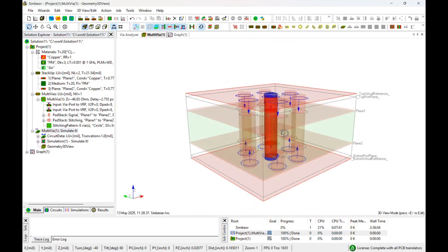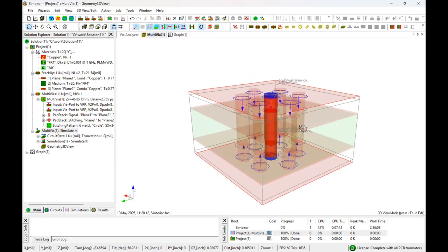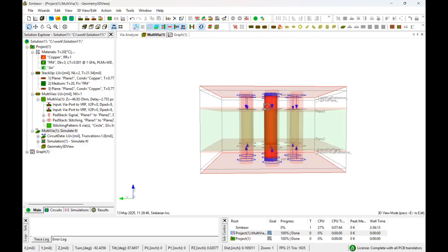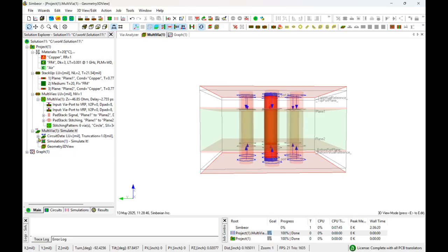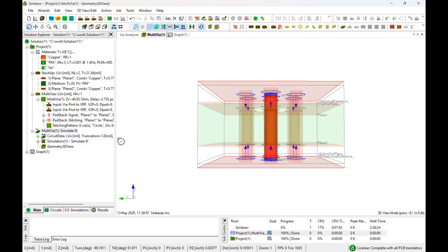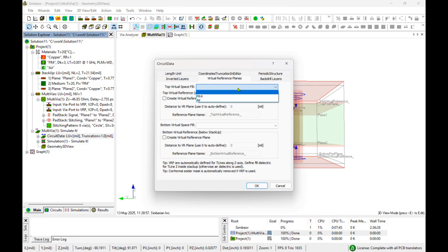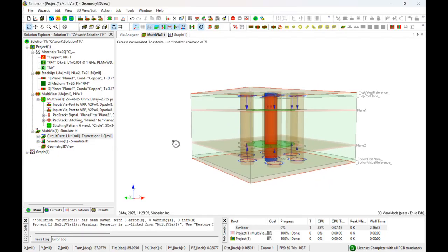So what it constructed is this geometry here. Essentially, this is the central part of the via going through just one dielectric layer. And one more thing, I need to fill this area here and here with the same dielectric. So far, this is what I called a manual process. Steps like this we're going to automate and make easier to do.